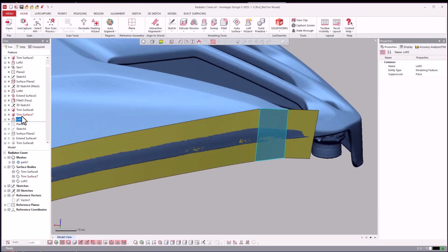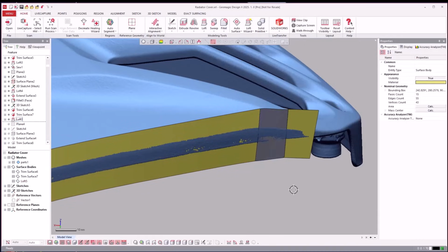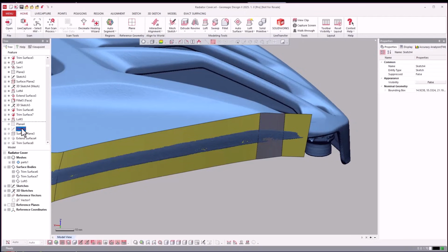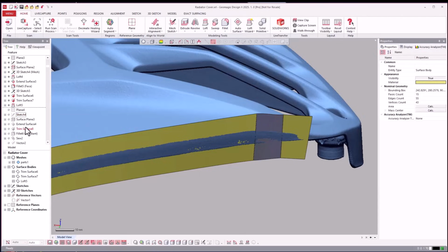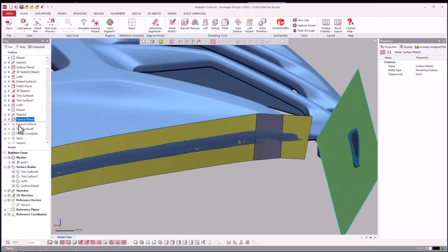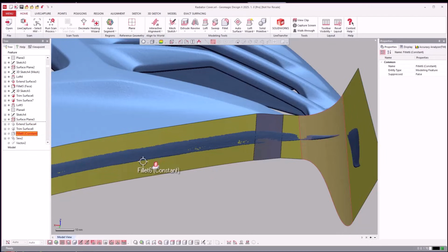So you'll see here that in this one, they did a trim. They went ahead and trimmed back and did a loft between. So that is a technique that we've covered in the past here, right? Where sometimes two surfaces don't intersect like we've done over and over and over here. Sometimes you just draw a curve on that surface, do a trim surface with a curve, then loft between them, and now boom, you have a connector surface between the two.